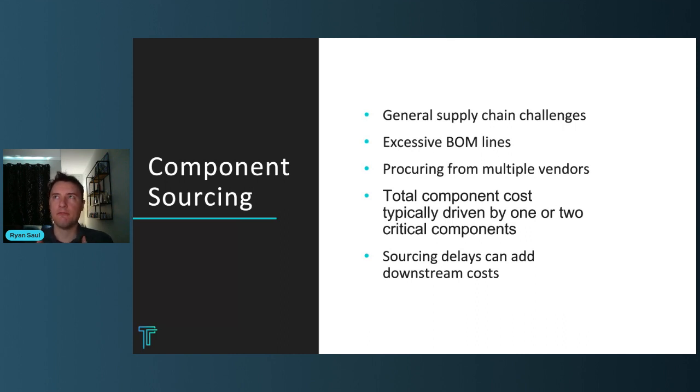Remember that for every unique BOM line that you purchase, they're going to purchase attrition that is going to be created during build setup, and then, of course, during manufacturing. Each BOM line creates another engineering artifact for your manufacturing team to understand and program. Each BOM line is another inspection artifact for each inspector, both automated and manual, to be able to understand and inspect against. And I highly recommend that you reduce your BOM lines if you can. Usually I'm talking about common passive elements.